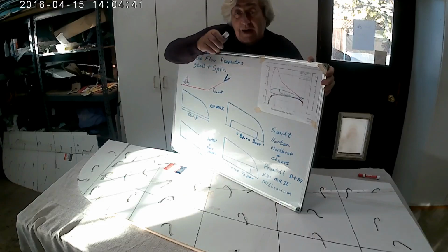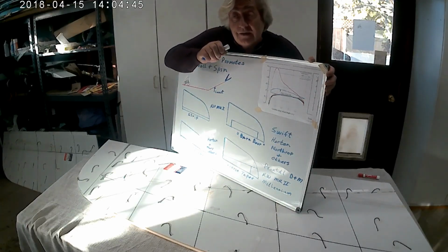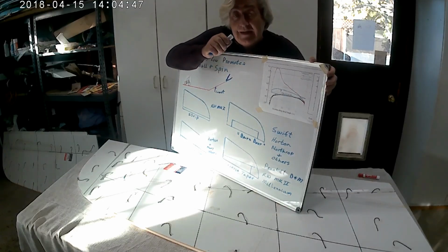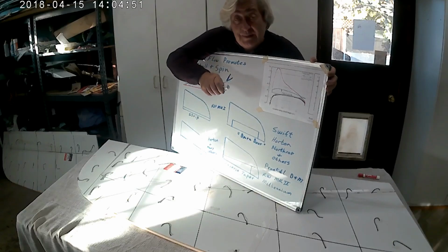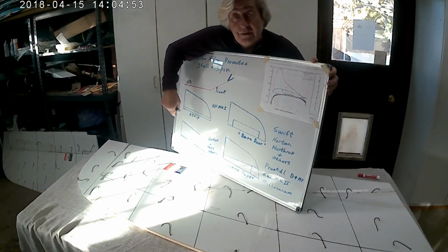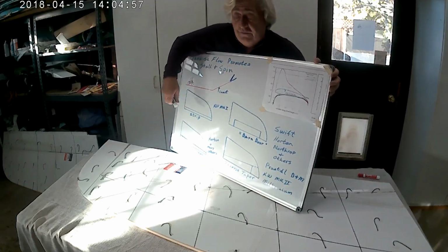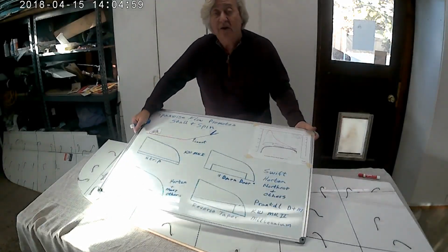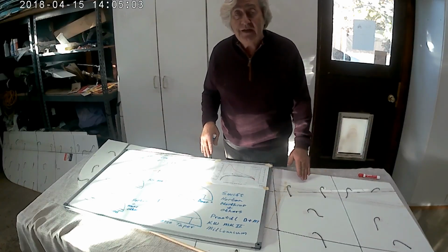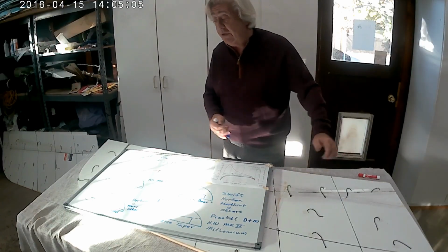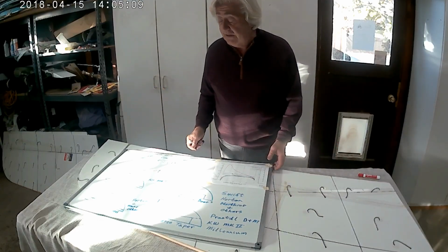So that's why tapered elevons, standard control surface shapes being a percentage of chord of the wing, are really bad. Because they're tapered going out like this, if it's a tapered wing, it just shoves the flow off the wingtip. So that's the three factors that are at work. One, just the mechanics of where the hinge line is relative to the flow, and whether you're shoving the flow off the tip or whether you're just kind of stalling it in place.